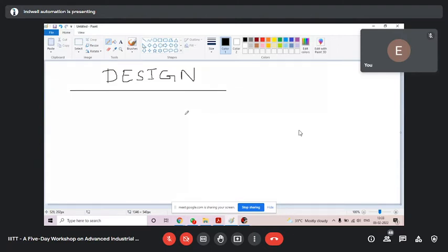For each address in your notebook, you have made a list of data. So for each address, you will have to create a tag. SCADA design won't accept your address X0, X1, but for each address you have to create a tag.